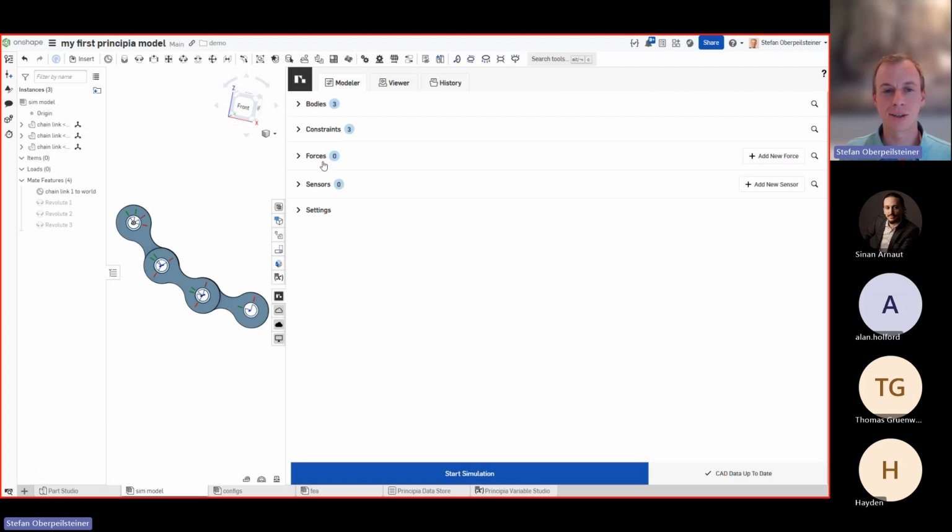So first, I'd like to create a sensor because, as I said in my introduction, one of the benefits of doing simulation, and especially multi-body simulation, is you can put sensors everywhere in your model, and that's not only cheap, it's free of charge because there is no additional computational power needed for doing this. It is something like a post-processing feature. But as you know every detail of your bodies moving around, you can, of course, compute any sensor reading you like.